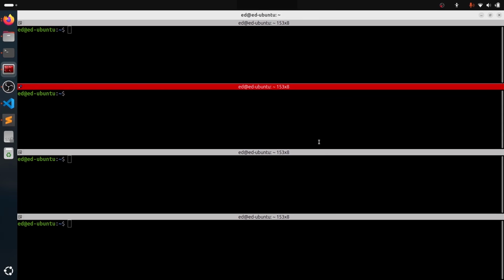Now that you have a URDF, a ROS2 control tag in the URDF to specify the hardware interface, which now is a mock component, and now that you also have a package with a config for the different controllers you want to use, we can actually start everything. I'm first going to do that directly from the command line. We're going to start each node one by one so you can understand what we need to start. And in the next video, we're going to actually create a launch file. Usually I recommend to start the stuff directly, understand what you need to start, and then add it into a launch file.